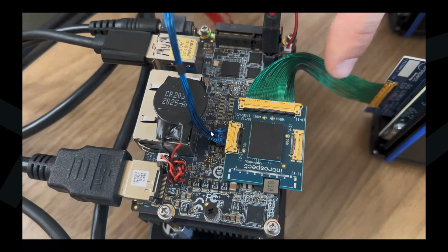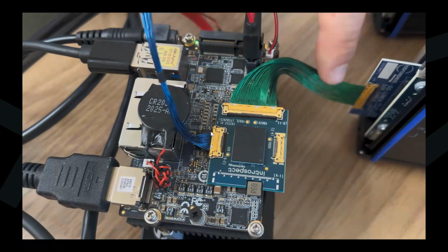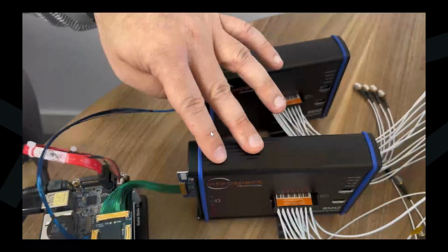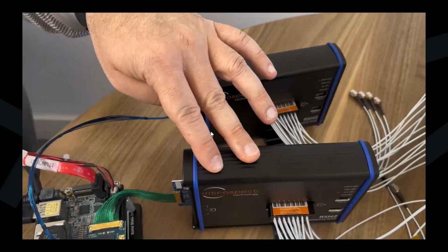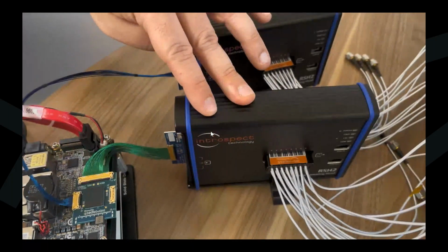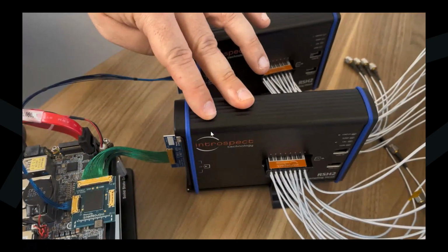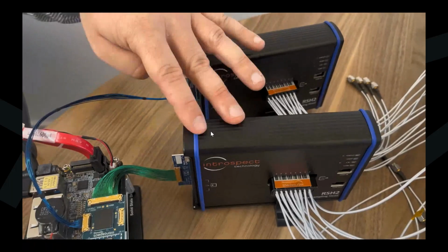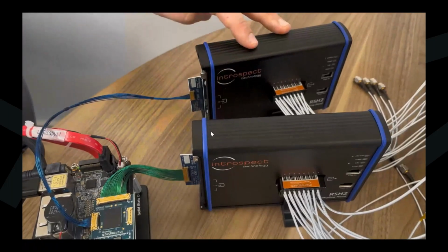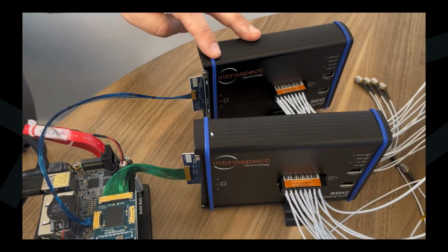The signals coming out of the interposer are going to two RSH devices. These are remote sampling heads, and they are active probe solutions that provide access to 12 channels simultaneously. In this particular demo, we're showing two of them. One, like I said, is connected to the DQ bus on the green assembly, and the other is connected to the CA bus on the blue cable assembly.